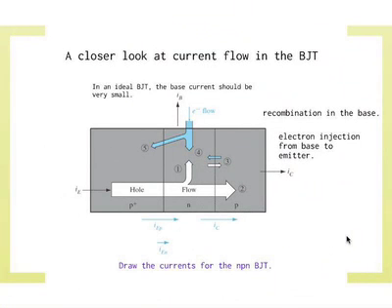This picture is probably one of the most important things that you need to keep in mind, because this will allow you to understand how the current is calculated. We'll look at this today in more detail, but let's go through this quickly. Again, you have the base, collector, emitter, and if you look on the right-hand side, it's nothing but a reverse bias PN junction. The base and the collector are a reverse bias PN junction. When you have a reverse bias PN junction, the only thing you have to worry about is reverse saturation current, and that is just because of minority carriers getting extracted to the other side. So in this case, you have these two small current components.